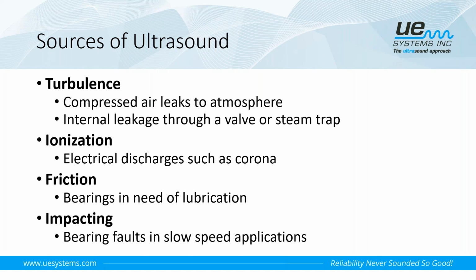Friction, so that's going to be with bearings in need of lubrication. When you have a bearing that needs lubrication, there's going to be an increase in friction, therefore an increase in noise. So if we're listening to that bearing while we're applying grease, and if we're watching the decibel level, we want to see the decibel level falling as we apply grease.